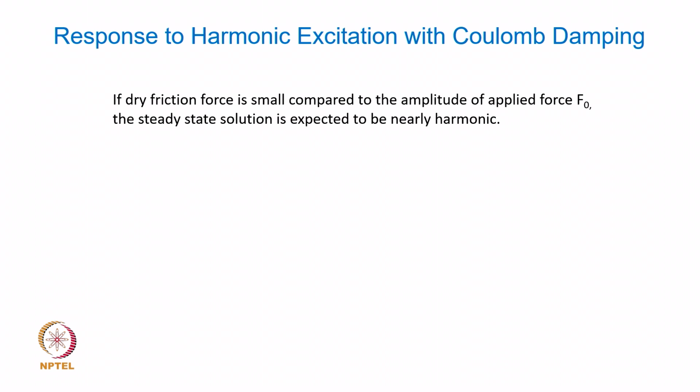But as we know and discussed, in case of a free vibration response with dry friction damping or Coulomb damping, the governing equations themselves are not linear, because the sign of the dissipating force keeps flipping during a single oscillation cycle.